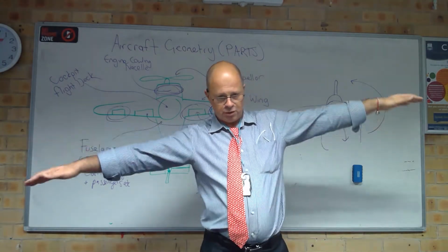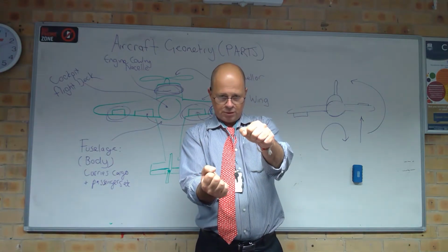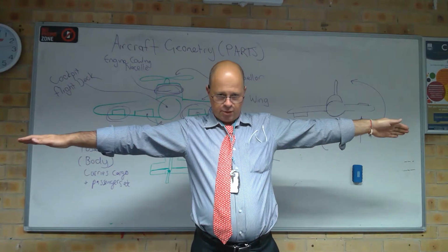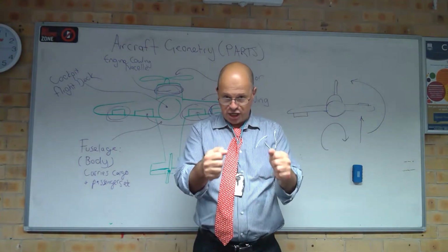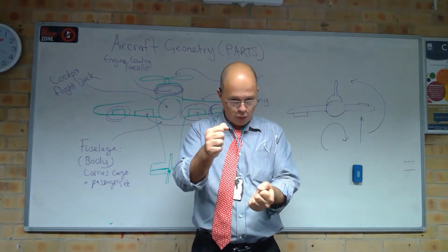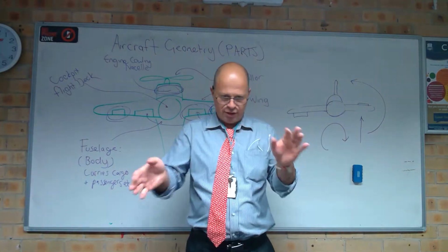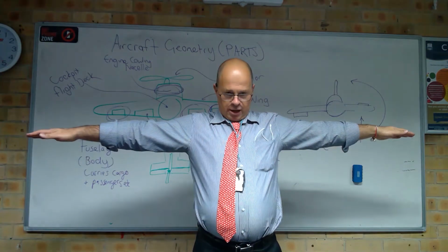Now let's stand up and pretend that we are going to roll to the right. What would happen is you would turn your control column to the right. This aileron would go down. If you're doing this in pre-flight checking, you'd be doing this to make sure you had correct sense on all the control surfaces. Turn right, make sure it does the right thing, rudder pedals, everything. You check them all. Anyway, I digress.